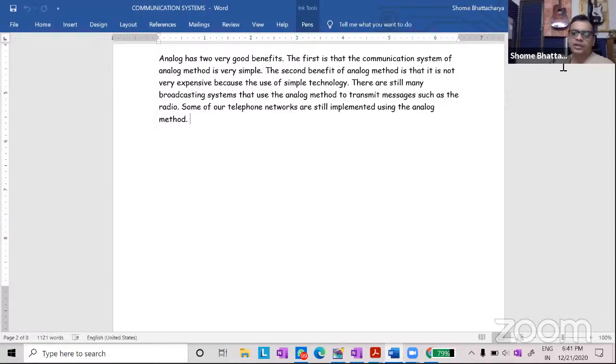So those advantages all come out because you have added that extra two layers: at the input signal level you have converted the analog into digital first and encoded the digital data onto the carrier wave, and back at the receiver's end, you are decoding the transmitted signal into a digital signal first. And that digital signal is processed by your system before the final output comes out.